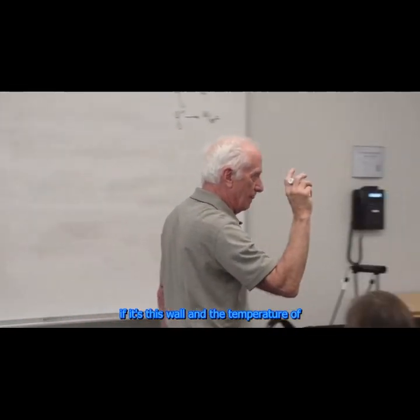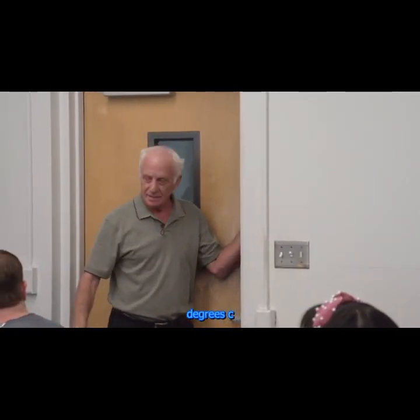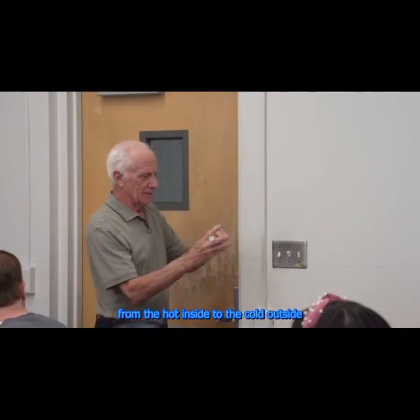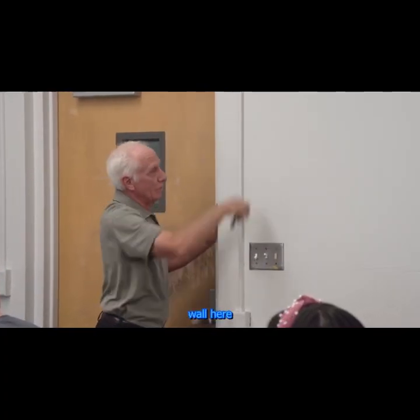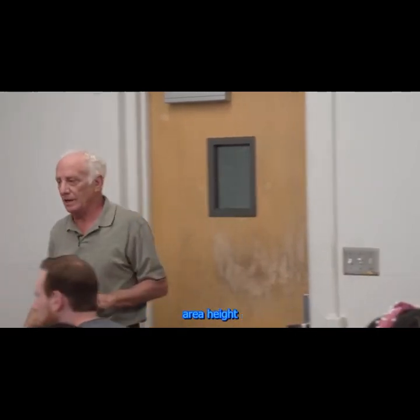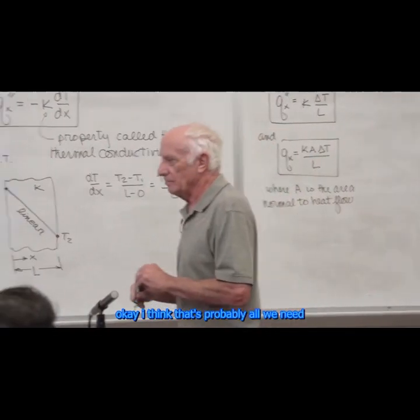If it's this wall, and the temperature of this side is 100 degrees C, and the temperature out here is 30 degrees C, which way is the heat flow? From the hot inside to the cold outside. Heat flow goes that way. What area do I use? The height of the wall here times the length of the wall. Rectangular area, height times length. Okay, I think that's probably all we need.